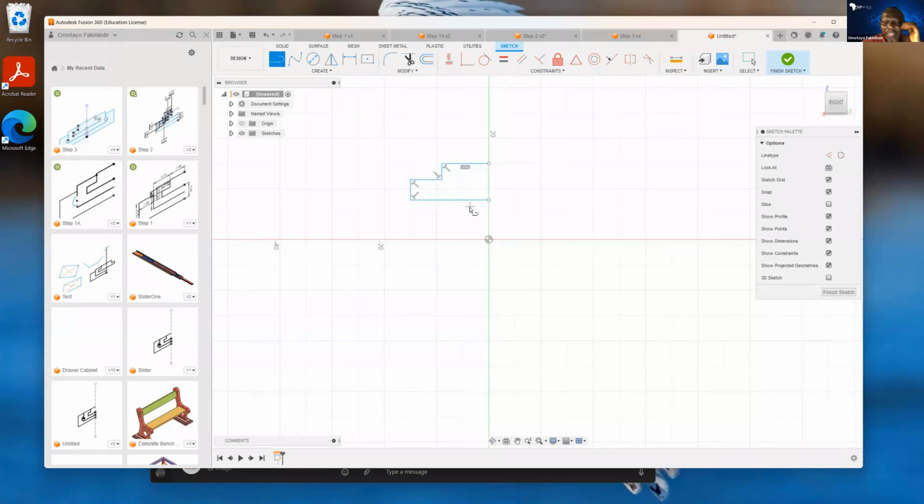I've done this. What I'm going to do now is put some dimensions to make it exactly what I want. Those dimensions are on one of the slides I gave you. So I will just say create dimension. The dimension, I want the distance between these 2 points to be 5.5. My own units are in millimeters, 5.5.